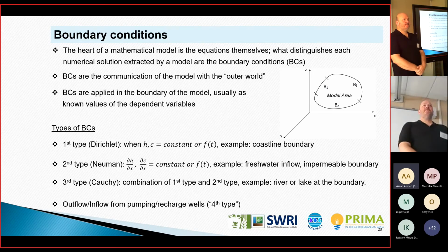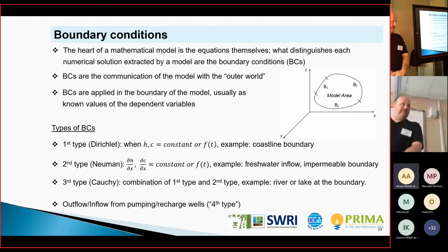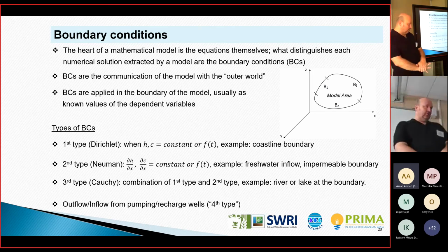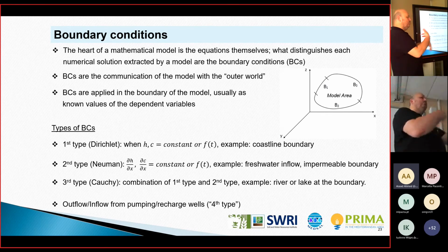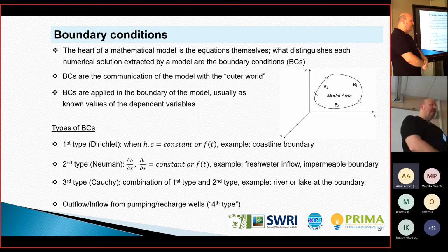Fracture and karst outcomes. In karst, may I use the same equation, or do I have to add some corrections? I'm not very familiar with karst hydrogeology in general, but you can't use these equations as they are. You have to use something more, probably, because the velocity is quite different. And yes, you need double porosity.